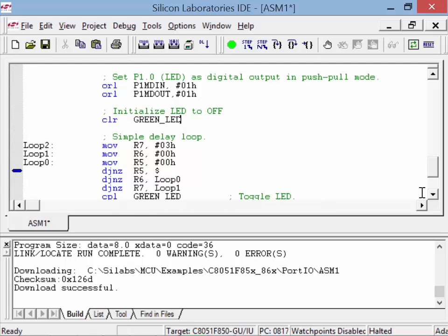We just hang that there, and then we decrement 6, and if it's not 0, we jump back to loop 0. If it's 0, then we jump down to the next one and decrement 7, and we just keep repeating. This is a series of 4 next loops. All this is we're just decrementing and jumping, if not 0, to the location. This just simply means stay in the same location. Just keep spinning. All we're doing is killing time. That's all those 3, 4, 5 lines are doing.